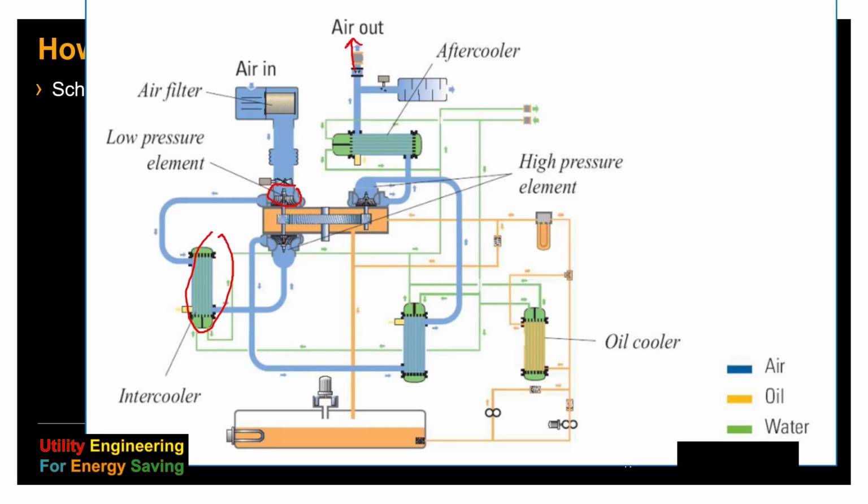By the intake, there is also a filter and a throttling valve. The impellers have different sizes and different speeds, the speed being higher than the motor, and there is a gearbox in between. The gearbox is lubricated by oil, but the oil is not getting in touch with the air stream.